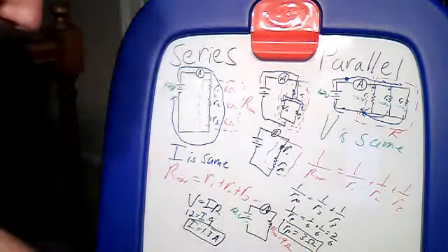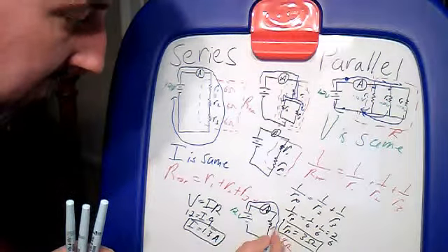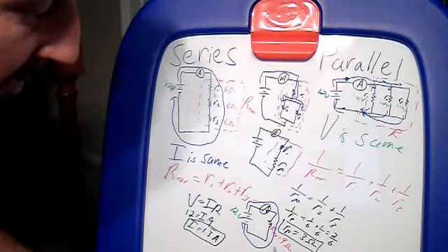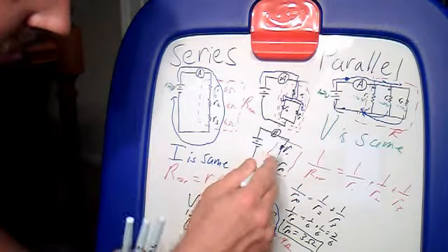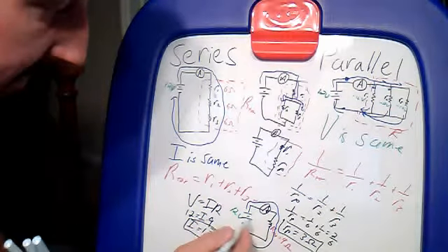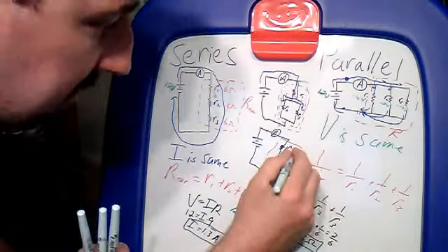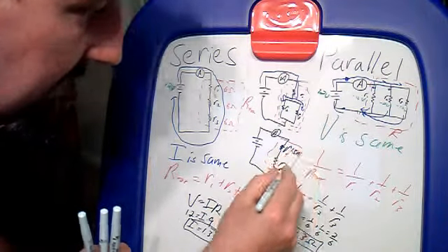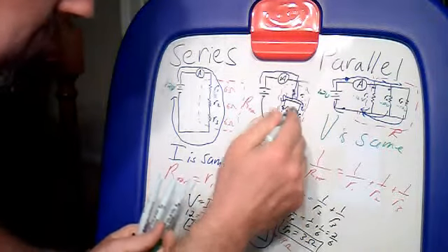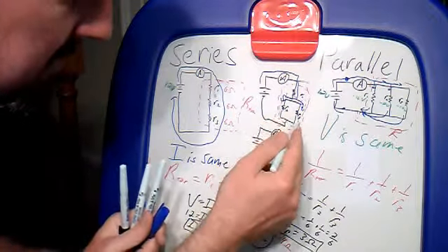Now, here's an important part. That's the current going through this circuit. And I'm pretending that this circuit only has one resistor and the current's the same everywhere. If I go back up to this one, R1 and RP are in series. So, if there's 1.3 amps going through that box and they're in series, this gets a current of 1.3 amps and this gets a current of 1.3 amps. However, if I jump back up, I can't assume that there's 1.3 amps in both of these resistors.